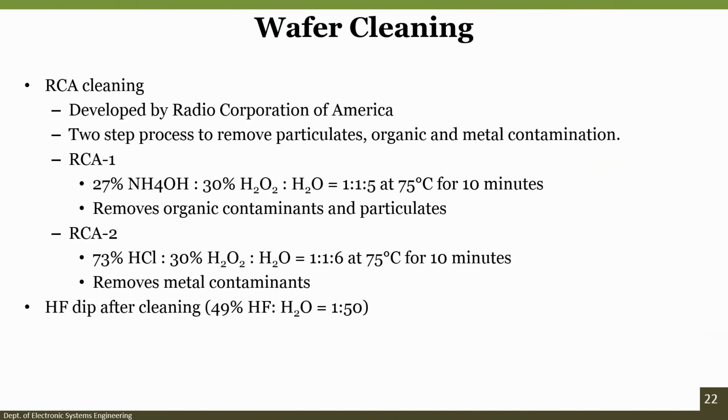Now, when you get a silicon wafer and you want to start the process, the first step is the RCA cleaning. RCA stands for Radio Corporation of America. There is RCA 1 and RCA 2. This is a two-step process to remove the particulates, organic and metal contamination.